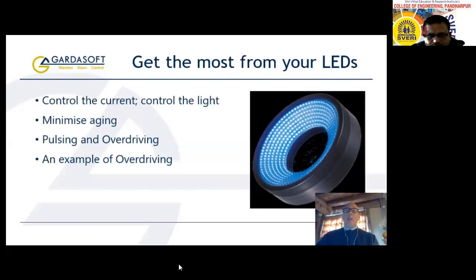LED lighting is generally specified as either 12 volt or 24 volt supply, but the brightness is determined by the amount of current running through the LEDs and not the voltage across them. This means that good current control is necessary to accurately adjust the light intensity. In addition, LEDs heat up during use, and this changes both their forward voltage and their efficiency, so that brightness will vary over time.